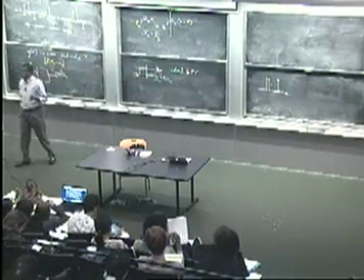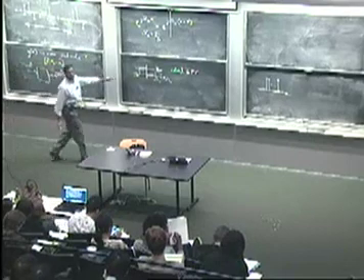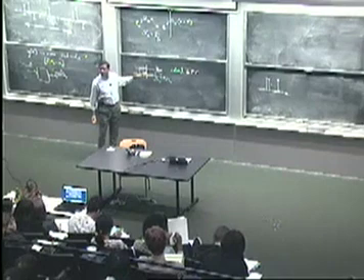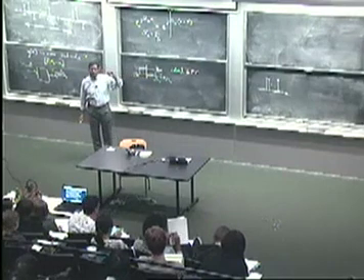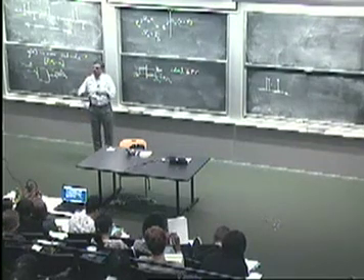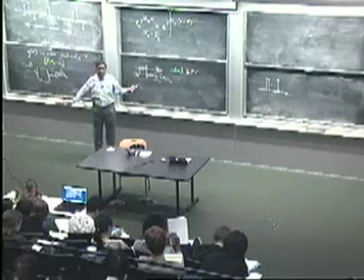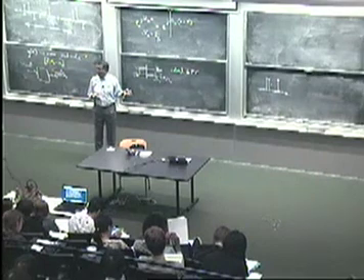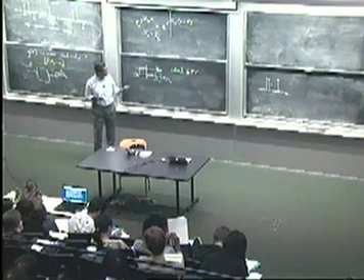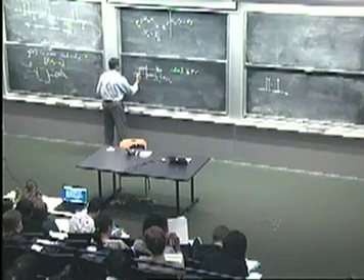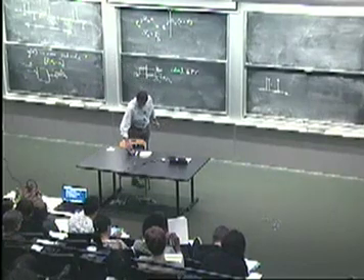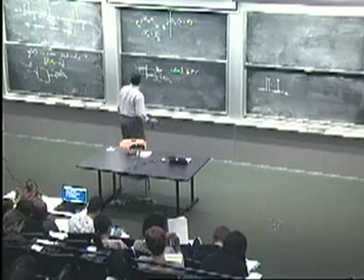And we know how to get approximations to this, right? Because this is not really implementable. If you wanted to implement this, what kind of unit sample response would you need? A sinc function, right? But extending infinitely in both directions. But we could truncate that sinc, and we could shift it forwards in time to get a causal approximation to this filter. And the resulting frequency response, if you compute it and plot it, won't look too different from this.